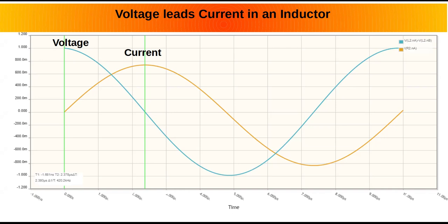Well, if it's in parallel, the maximum resistance of this parallel circuit is going to be whatever that resistor is. It's going to be that or less, because it starts essentially at zero, because your inductor is a short circuit at zero. If you had it in series, then you've got whatever that resistance is and a varying reactance that's going to be anywhere from 0 to infinity. So yeah, it would have a different effect. I'm not sure how you would calculate it, but you don't have to calculate that one. Sorry, I didn't mean to go off topic. That's okay.